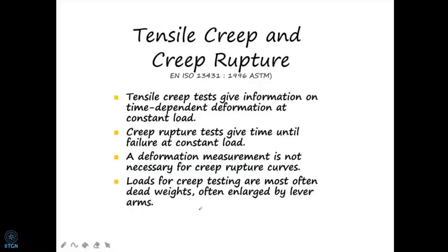So we'll now see the effect of creep. Now this is done, of course, as per EN ISO or ASTM. The main thing is that the tensile creep, that means creep under tension of the geosynthetic, gives information on the time dependent deformation at constant load. What do you mean by that?